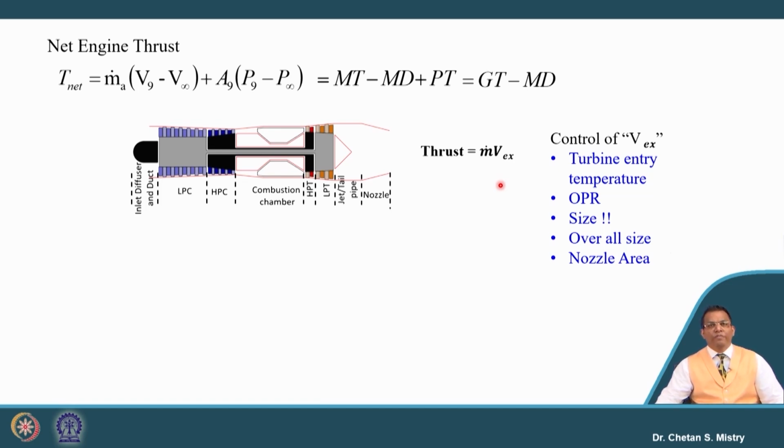So, this is what all we know up till now. Now, the next possibility we have is mass flow rate. The question is what we mean by mass flow rate and how do we increase it. Suppose I consider this is my engine, and if I want to increase my mass flow rate, you can understand that for that configuration we need to increase the size of the engine, okay, and with that our exhaust velocity will not be giving the benefit in terms of increase of thrust.